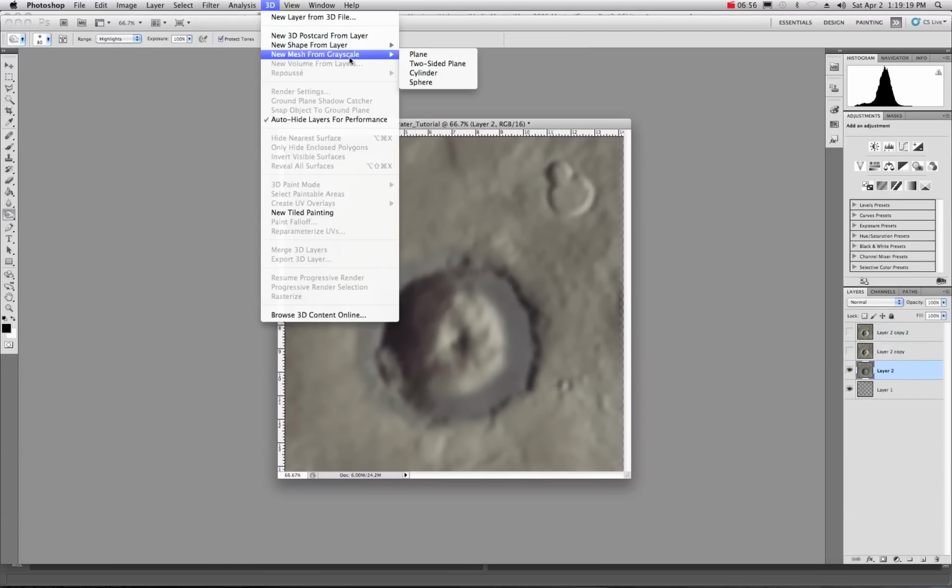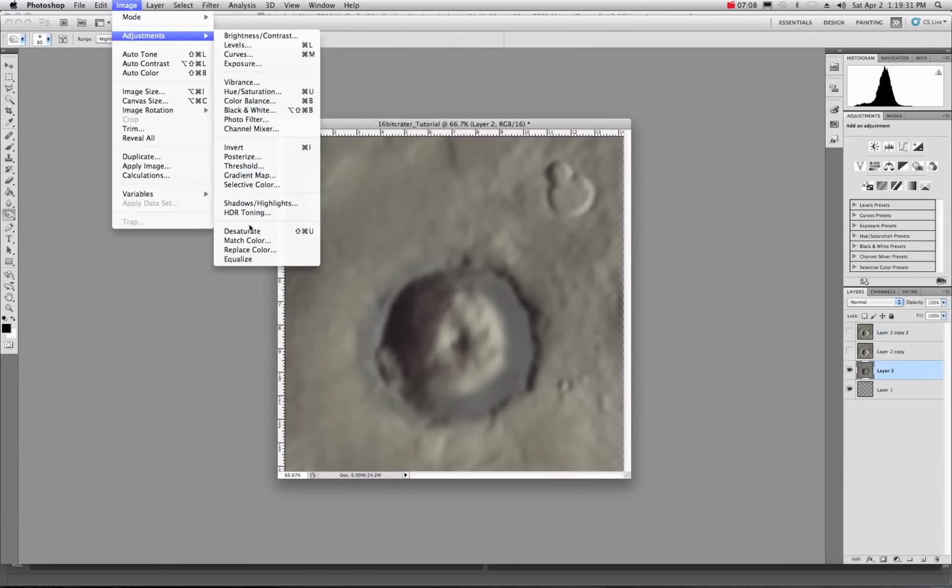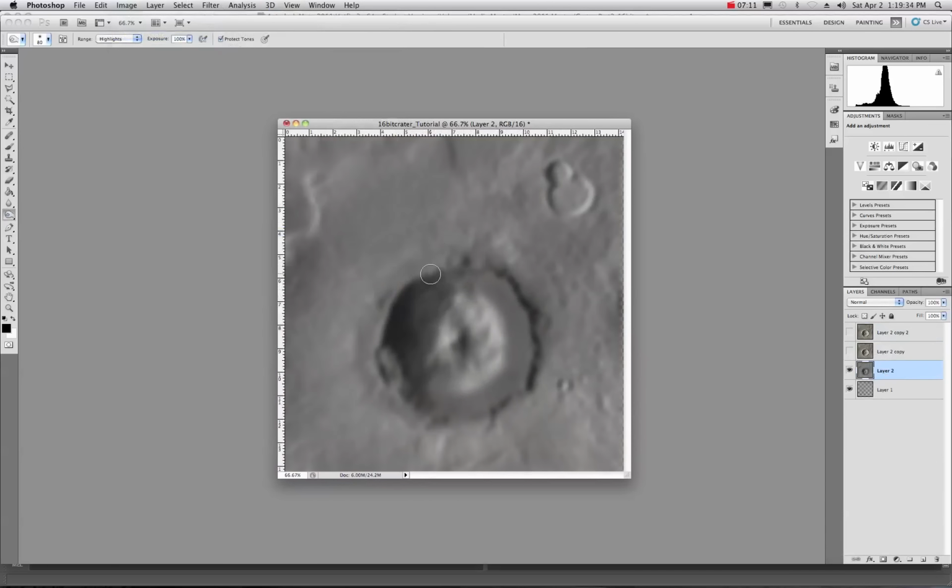See, it says grayscale. One thing that we forgot to do, and we want to make sure that you actually do, is come in and desaturate that layer. So let's desaturate that layer. Okay, now we have a black and white, and that's what we want. All right. Now you can also tell that in here, the values from here to here, we should actually make this darker in here to match that. So it doesn't have a stair stepping going on with the height and the width.